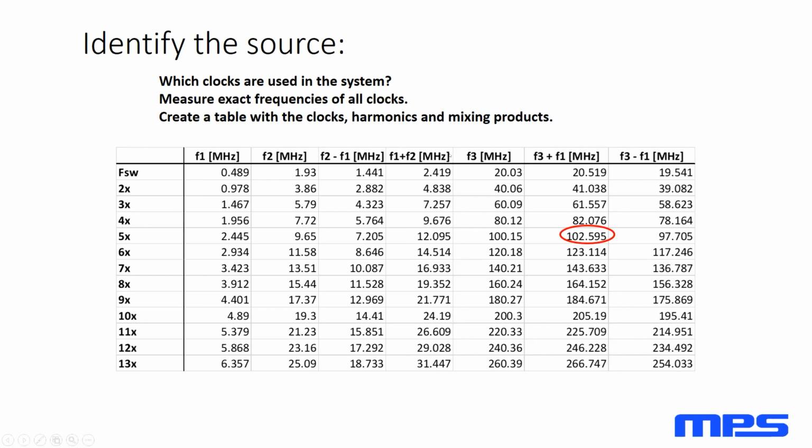And you should have the different variations of the frequency. It just depends. When you get to the layout, if none of these things are near each other, you're likely not to have any coupling and you won't have any mixing products. But if you have a SPI clock or a DC power supply, the switch node could couple to something else, and it's possible that you end up seeing some of this.